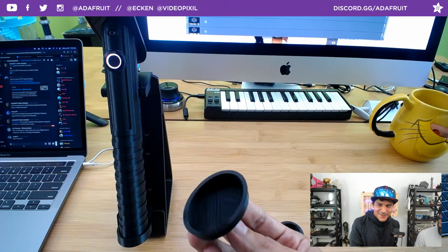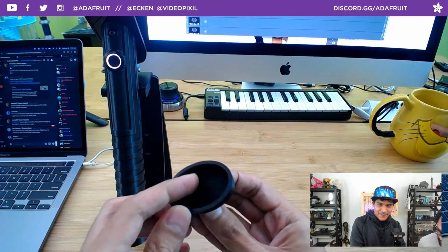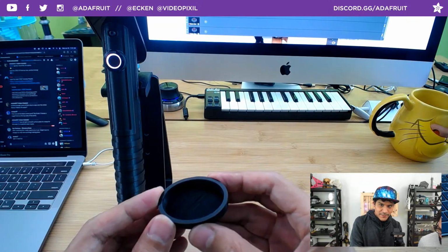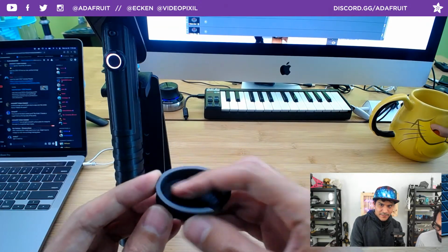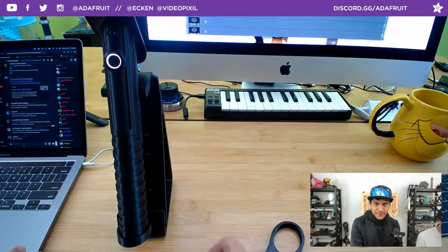Now you could use support material for this, but it doesn't matter. The printer should be able to catch that, so that is printed without any support. Even if there's overhangs, it shouldn't interfere with anything. Right, because what you're touching is the edge here. Just trim it off. So there you go, there's the pommel.